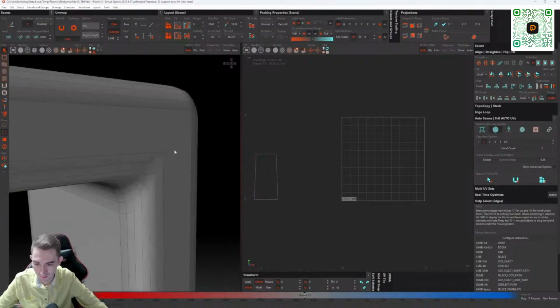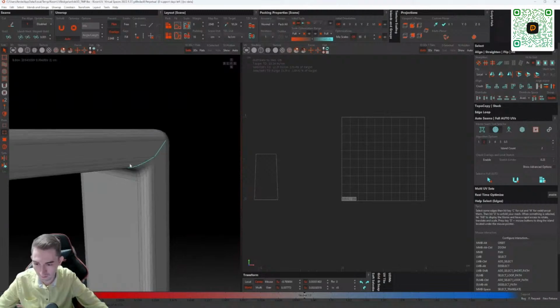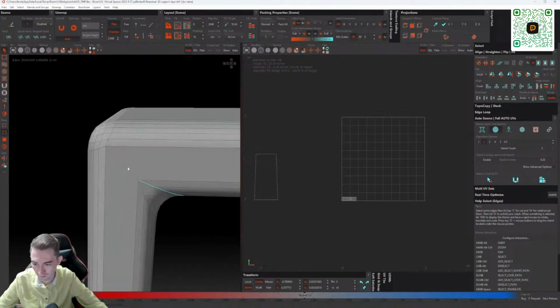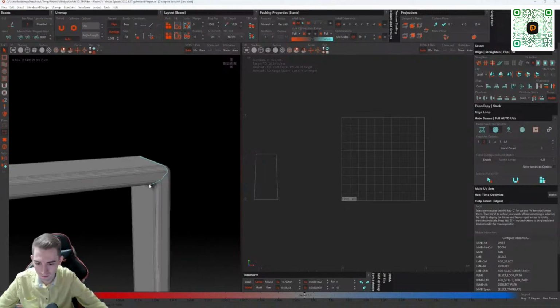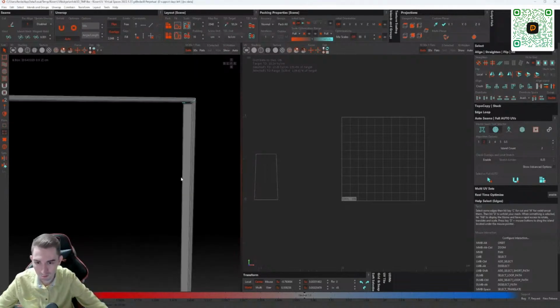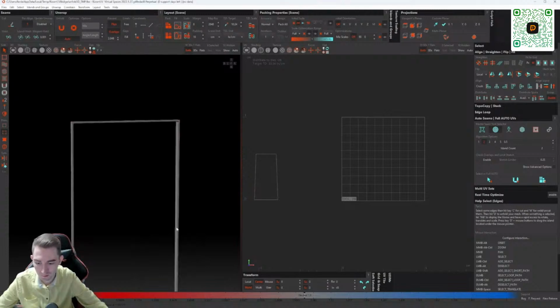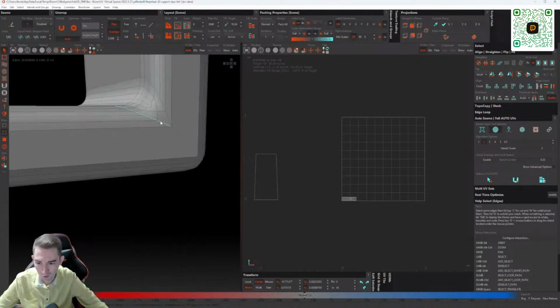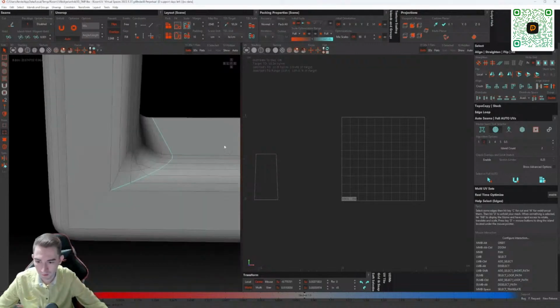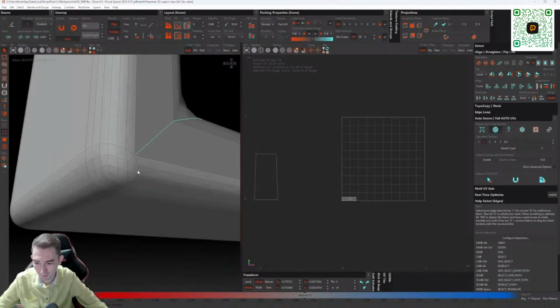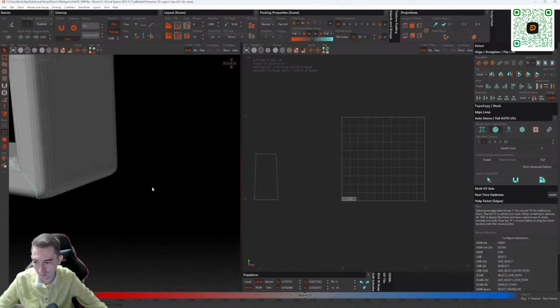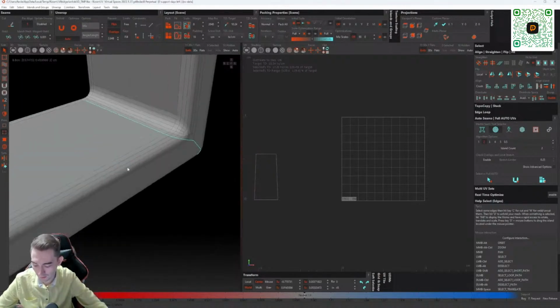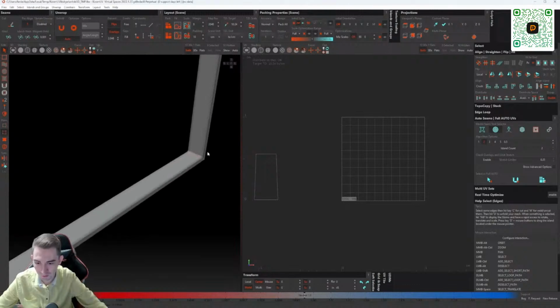We'll do the same here. We do this because there is such a closed figure here, it normally will not unwrap automatically. So we need to help a little. We select with the magnifying glass with a double click, something like Edit Poly, and press the C key, that is, cut.